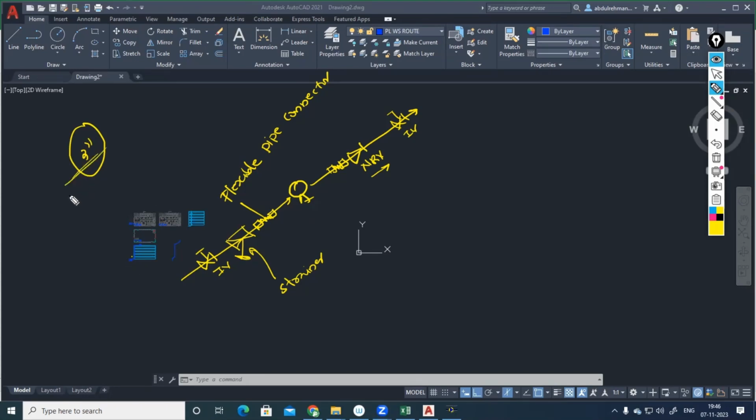But when we select the pump from the technical data sheet, in a real scenario, the pipe diameter that we have designed and the manufacturer's machine inlet and outlet diameter will vary. So if our designed pipe diameter and the pump inlet and outlet connection are matching, you don't need that fitting. Otherwise, in the suction, you always need an eccentric reducer. In the delivery, you need a concentric reducer.